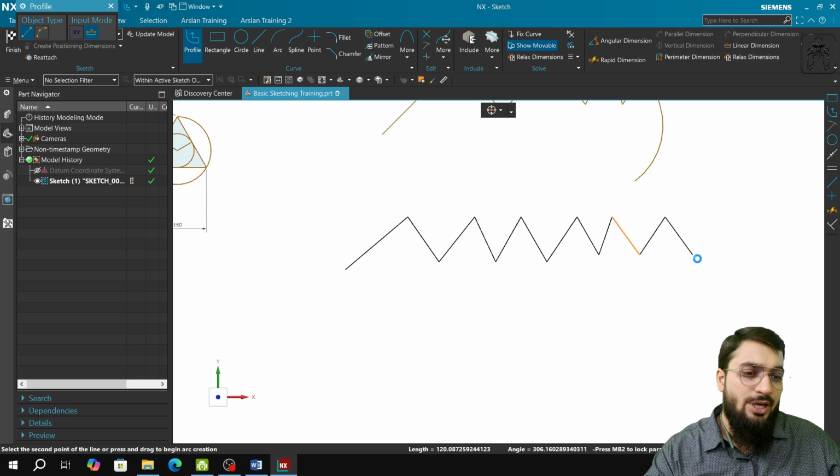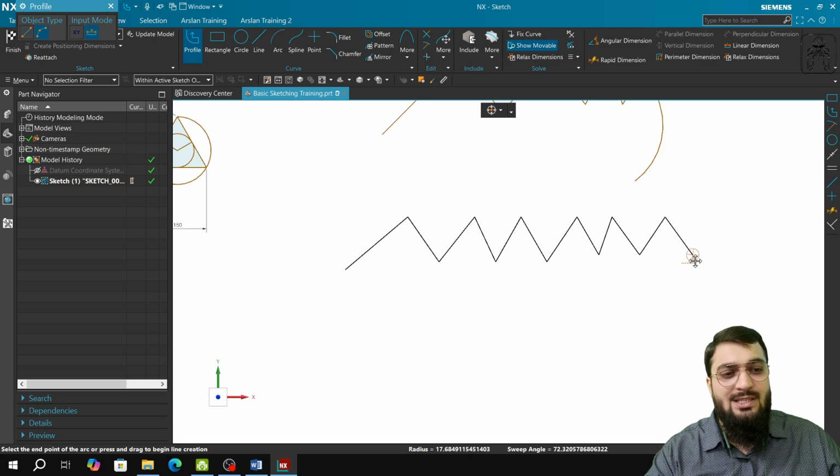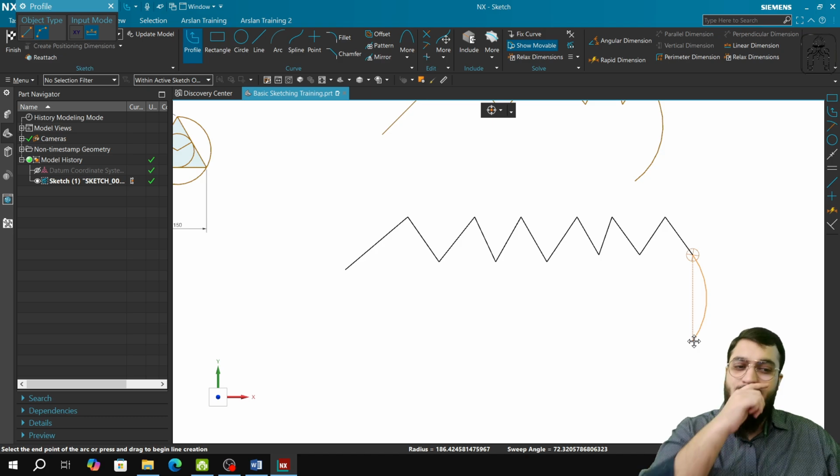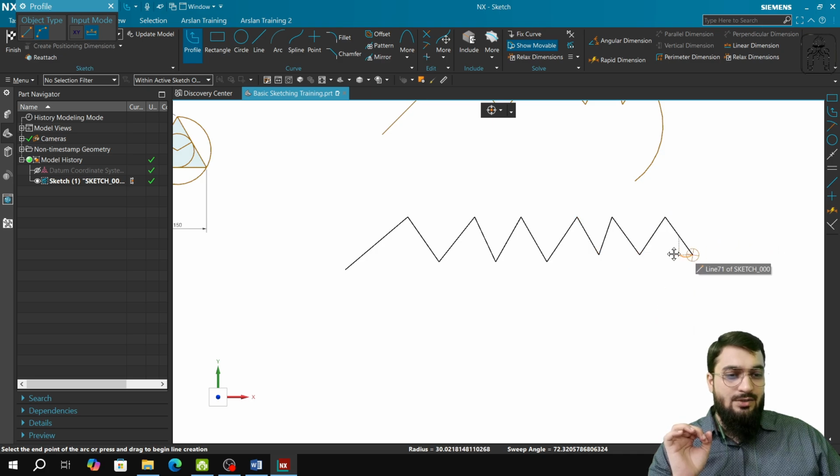And when you have to create an arc, you press the left click and hold it till the time you have created the arc which you desire. So I am currently pressing the left click down, and I am moving my mouse to change the cursor location, and the arc is getting changed according to my cursor behavior.